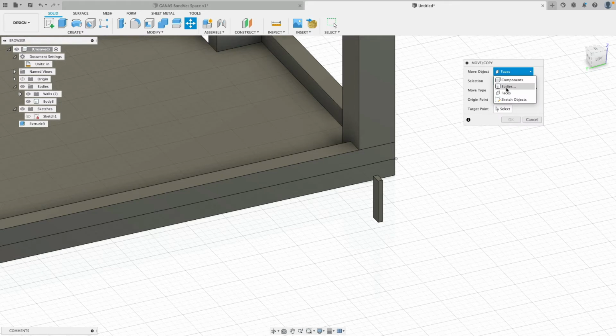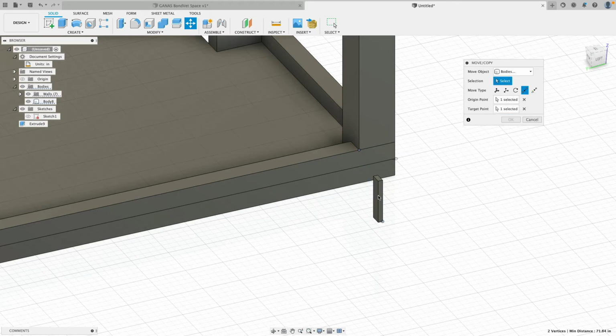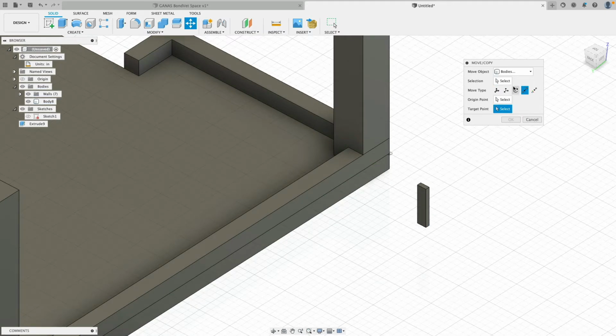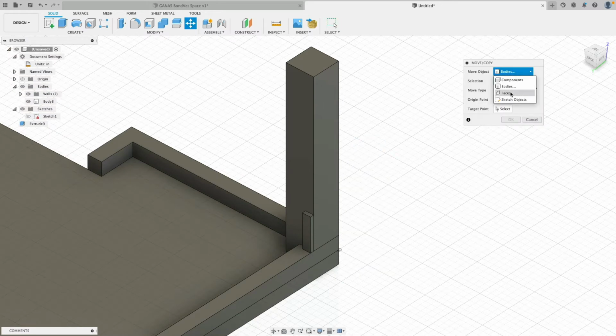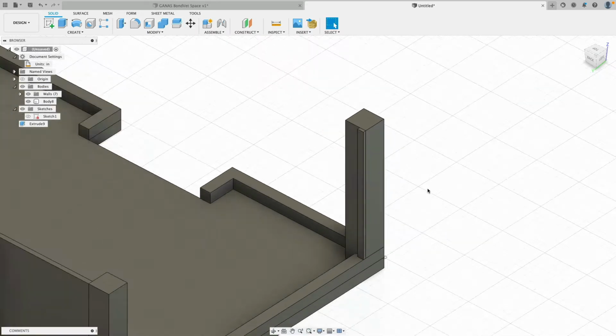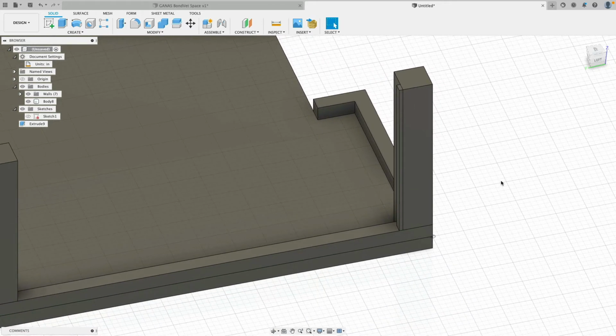This piece, I will, via the move command, move into this corner. Okay, maybe one more time. U to there. Thank you. Then we right-click, repeat, face adjustment. We would like to move this face up to there. Very good. Yeah, so now we have actually our vertical part.